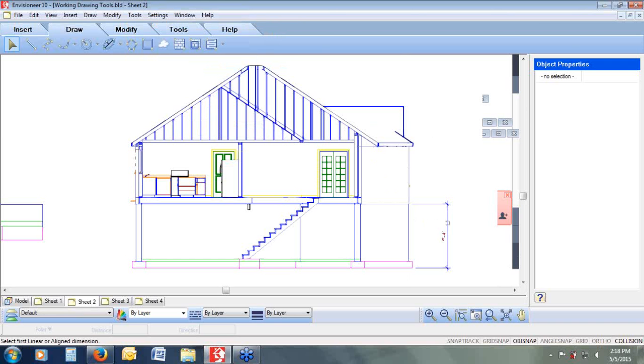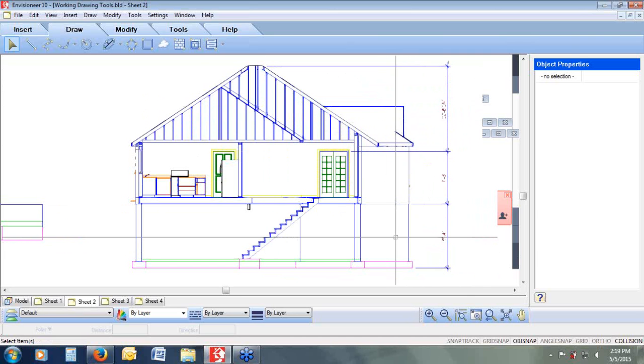It recognizes that I want to, first of all, down in the lower left-hand corner, pick the linear or line dimension you want to continue from. I pick this one. It says, OK, I'm going to start my dimension right from that point. See how it's already drawing a dimension? So from there, I can pick to the top of my doors, or I could pick to the top of my roof again. Right-click and tell it I'm finished.